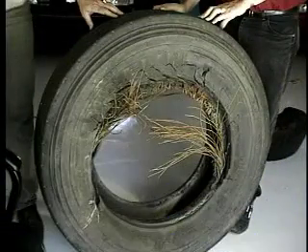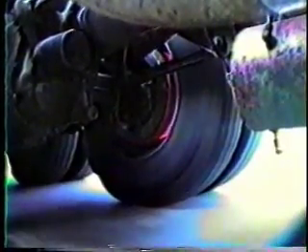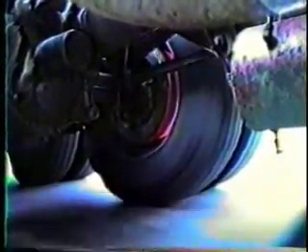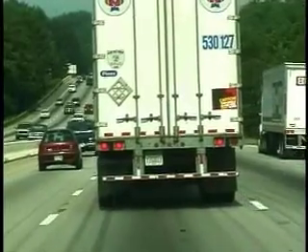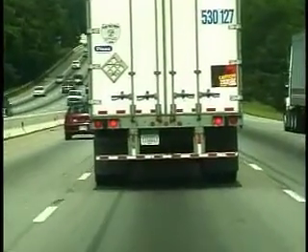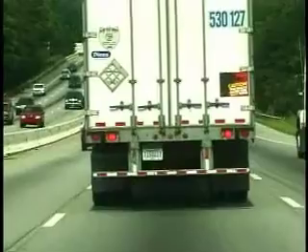The next condition to discuss is bead damage due to brake heat or burned beads. This condition is caused by extreme heat created in the brake drums during frequent brake applications with little cool down. The condition can also be aggravated by over-adjusted brakes or mechanical problems with the vehicle braking systems.